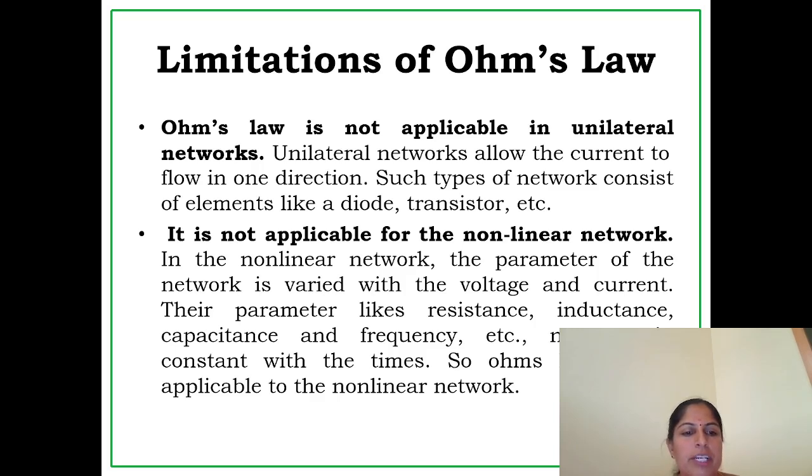And coming to the limitations of Ohm's law. The first limitation is that temperature should remain constant. Ohm's law is valid only if the temperature of the conductor remains constant. When current flows through a conductor for a long time, it heats up. As the temperature increases, the resistance also changes. Since resistance is no longer constant, the relationship between voltage and current changes. Therefore, Ohm's law is not valid when the temperature changes.